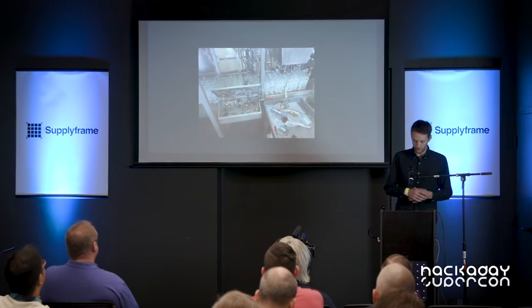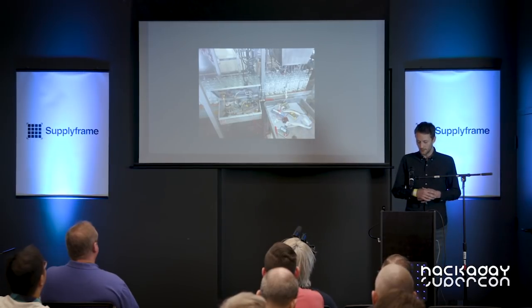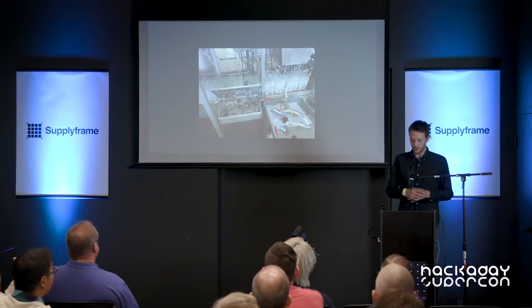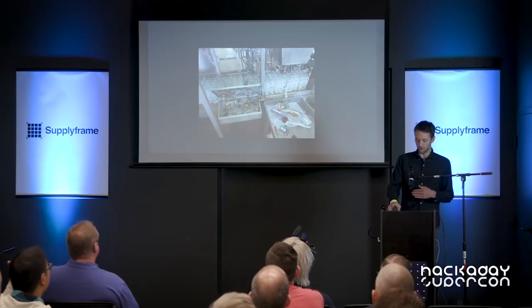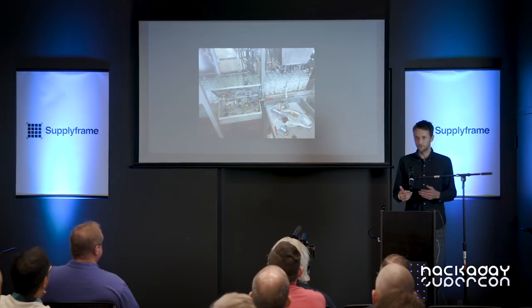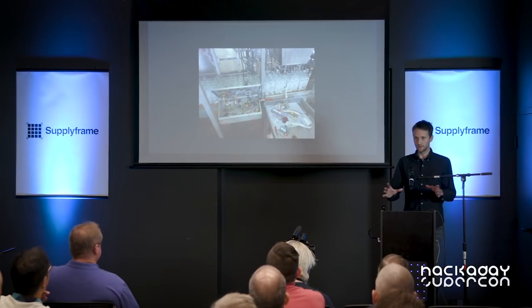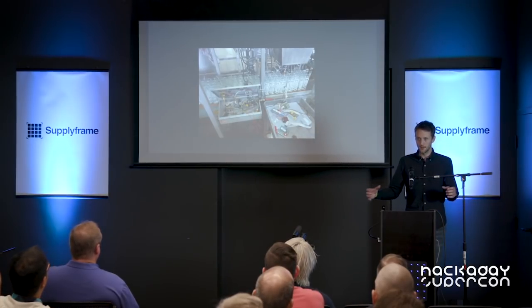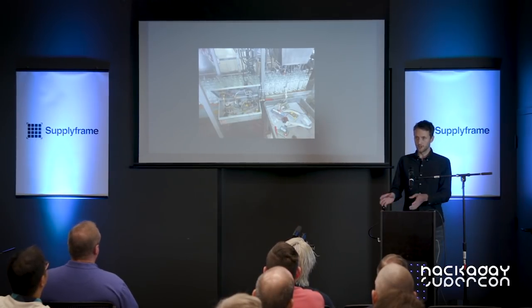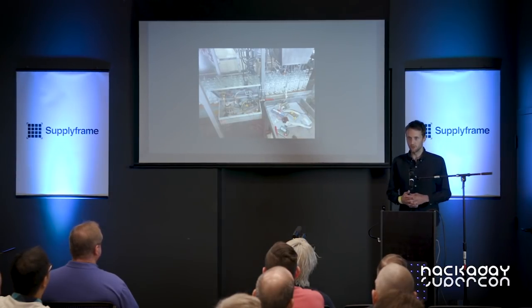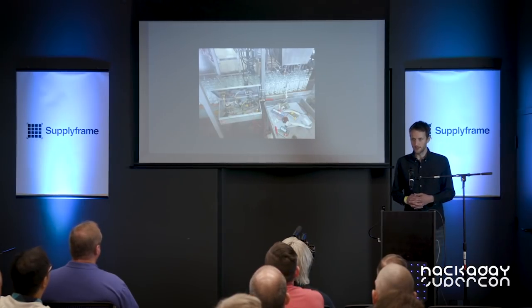So this is one of the first setups, the first tests. At this point, it was not using a line break sensor. You can see this sensor is kind of propped up with the wire there by the jars. That is an infrared reflectivity sensor. The idea is that it senses the curvature of the glass as it passes and can stop it at that point. Because at this point, all the jars are jammed together, and they are varying distances away from the edge of the conveyor, because they're all just put on there by someone. So you couldn't use a line break sensor. But since then, we changed it so there's a gap in between, and that simplifies a lot of things.